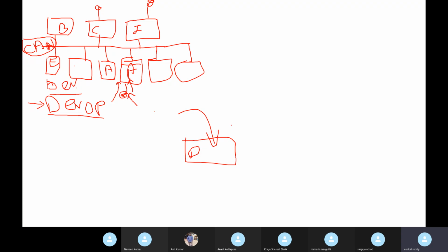The actual functionality is the crash zone sensor getting the signal, the pressure signal. If any accident happens, the pressure will come, some PSI. We will write the code. Based upon the pressure, it will deploy the airbag. This is the actual functionality.